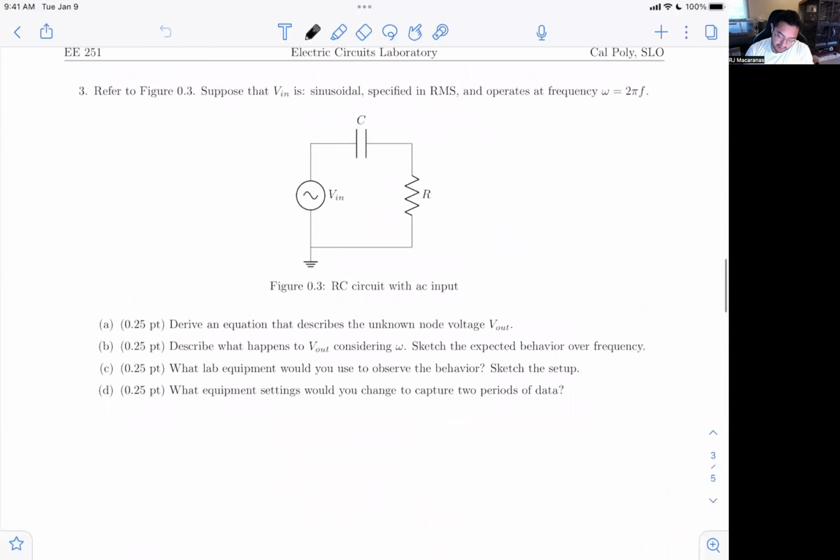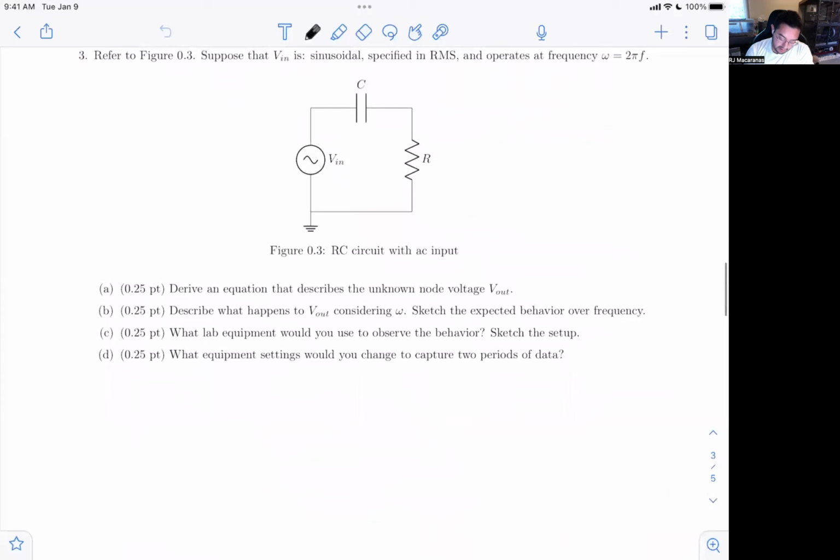It's kind of like the same idea, we just have the capacitor first now. So I'm actually going to skip ahead and use the voltage divider principle. So V out is a ratio of V in. And what ratio? We're looking at R divided by that equivalent impedance.